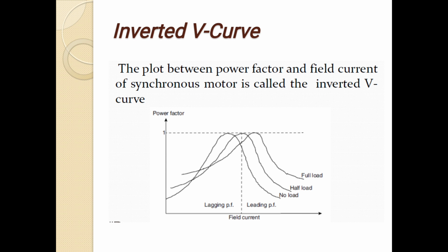Now I_L equals I_A for the star connection, and I_L divided by root 3 equals I phase for the delta connection. The power factor formula is cos phi equals cos of tan inverse of root 3 times (W1 minus W2) divided by (W1 plus W2). This is the value of the power factor.